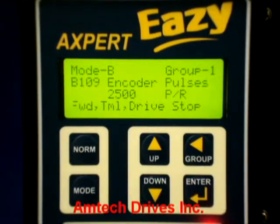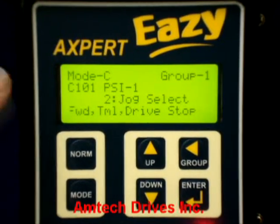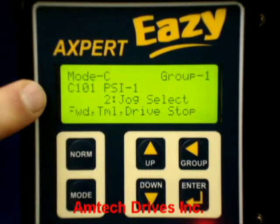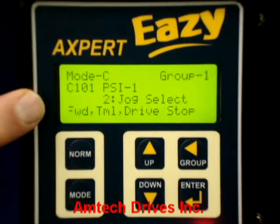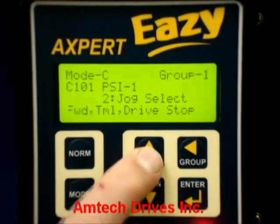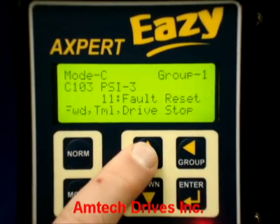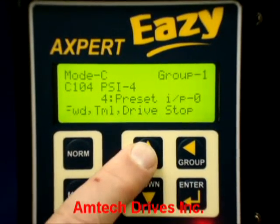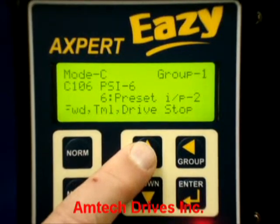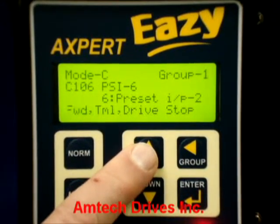Many of the parameters in the drive, especially in the C mode as we're in now, are only set up at the initial startup on the drive. In this case, C101 is what you set for the digital input. In this case, it's jog select. If we go through digital input 2, E-stop, the default reset, the preset speeds 1, 2, and 3. So those are the default parameters, and it makes for easy selection and changes to the digital inputs by just changing those parameters.